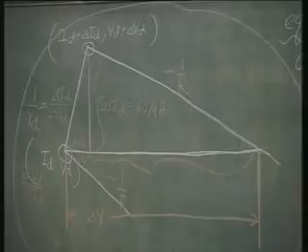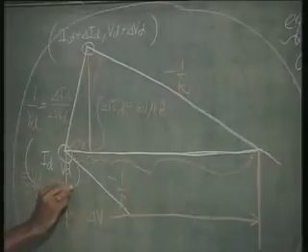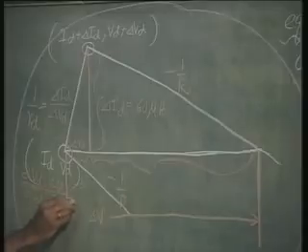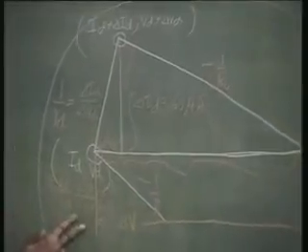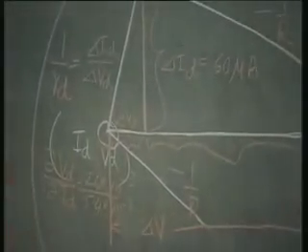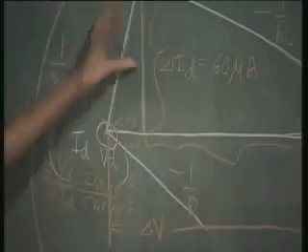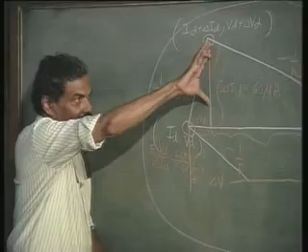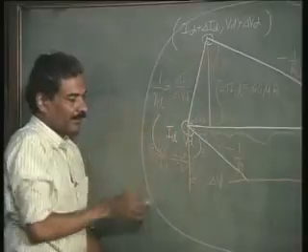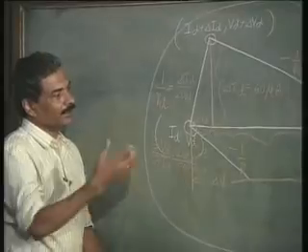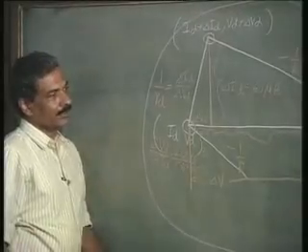So, this is going to be 26 millivolts divided by 5.4 milliamperes. So, we had evaluated this as 26 by 5.4. So, that is the resistance. So, that will determine the delta Vd, which is, delta Id is 60 microamperes, delta Vd therefore is equal to 60 microamperes into Rd, which is given as 26 by 5.4. So, that is the answer that we got in the analytical expression also.